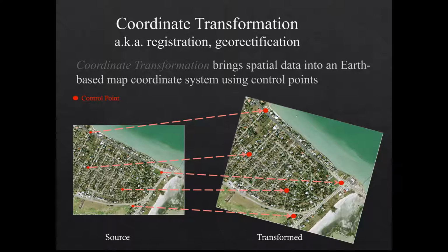What would happen is that the image will not show up in the right place on Earth, but it will instead most likely be placed at the intersection of the equator and the prime meridian. This is because the aerial photo you took is not referenced to any location on Earth. In fact, the picture has its own arbitrary coordinate system, which starts from 0, 0, typically the lower left corner, and it increases in positive direction along the x and y axes.